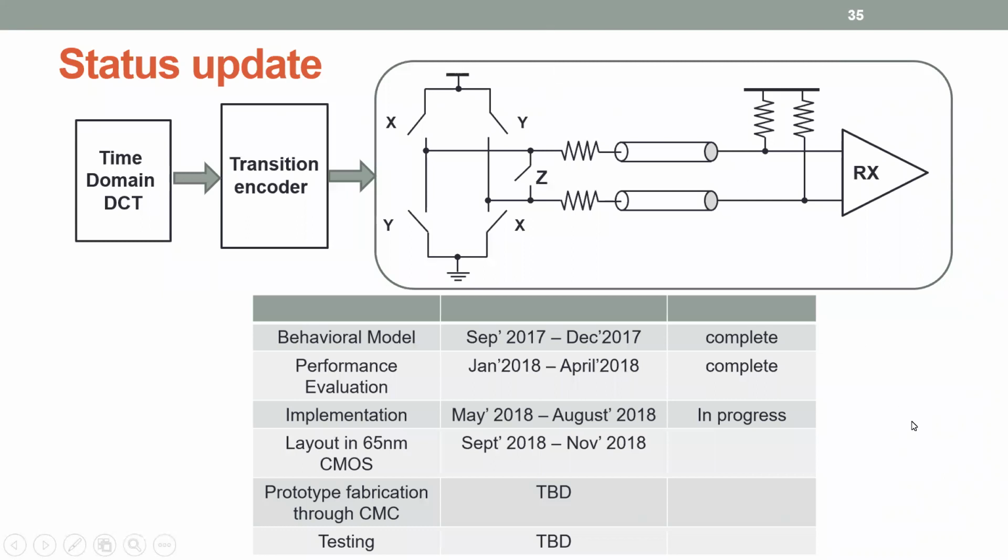So regarding the transition encoding to minimize power consumption, one thing I am aware of regarding schemes that attempt to use that is that if you have a long run of 1s or 0s, you lose sync. How do you keep synchronization? Oh, that's a very good question. So the transitions are used for timing recovery.